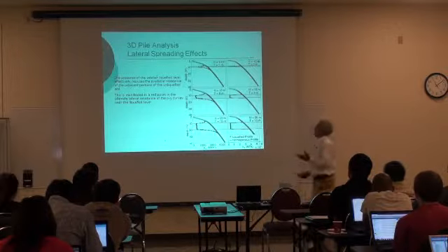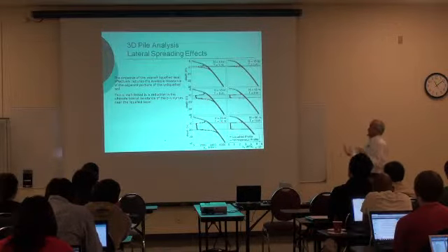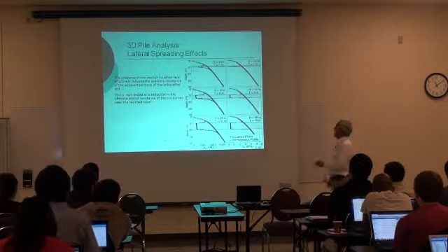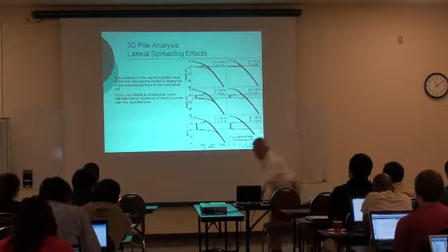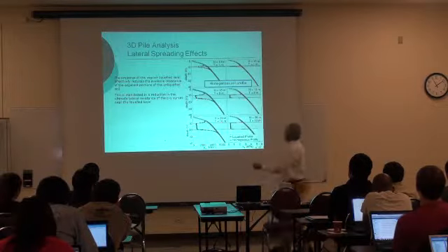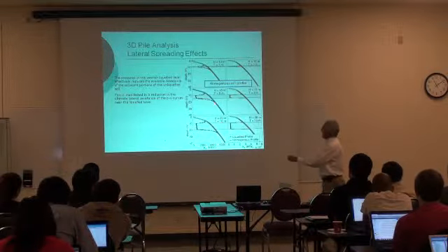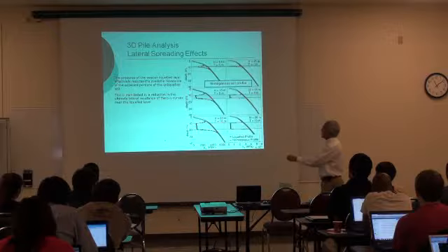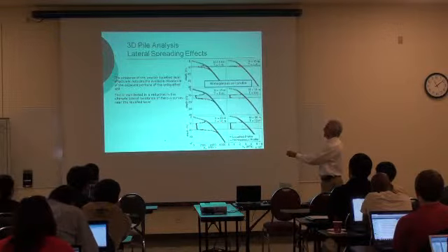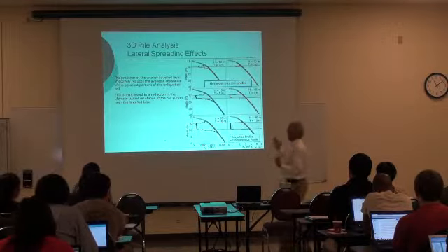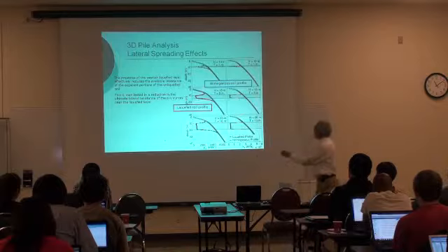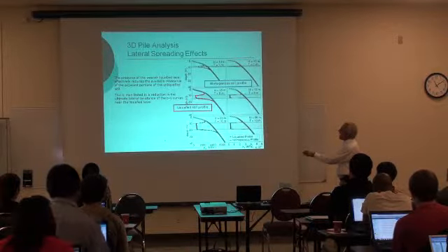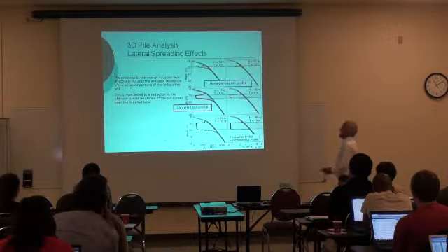And this shows you, for example, the effect of a liquefiable layer on the PY characteristic parameters. Here in blue, I am showing how the P ultimate changes with depth if there is no liquefiable layer. And on this side, we have the stiffness. It's not the P ultimate, but the stiffness. And the red tells you how the P ultimate behaves if you have a liquefiable layer.